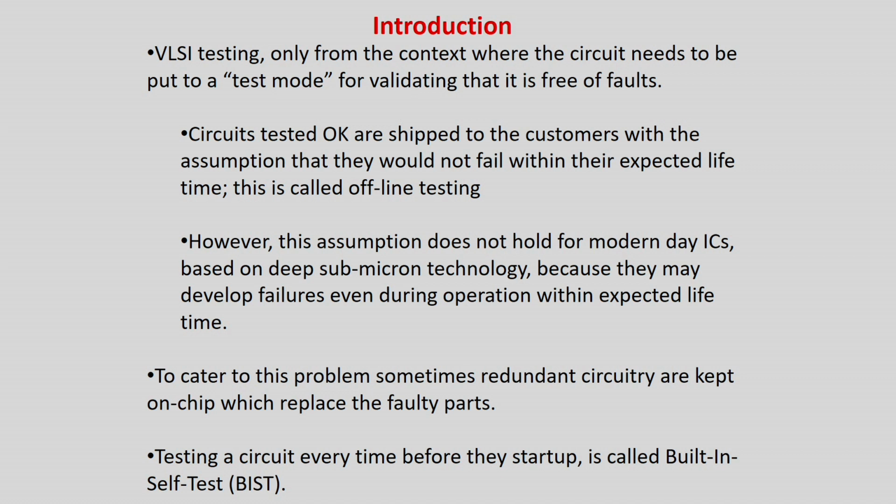I will tell you why it is called built-in: before it starts its operation, it tests itself so that it gives you some confidence that it is normal. That gives you more confidence that even failures which may occur after the deployment of the system can be detected in that manner. If a fault is detected, it can flag an error, or if there are redundant modules they can be switched on. If there is no redundant module, like in a home appliance such as a mobile phone, a washing machine or a simple microwave controller, then it will give you an error, tell you that this chip is not working, and some vendor will come and replace it.